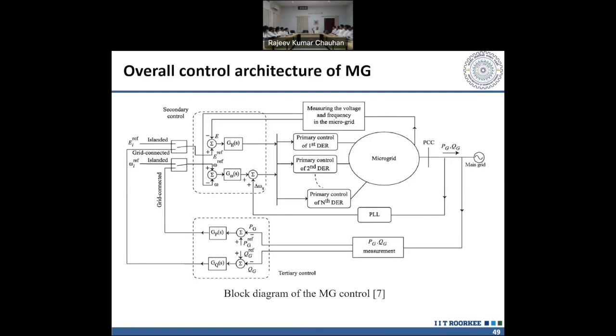So that is my droop. We call it a droop characteristic. This droop will appear in the voltage as well as in the frequency. So this might now from 250 become, let's say, 300. So what will happen? In this line, you will fall down. That means you are coming down to that particular droop. So that droop control is my primary control.